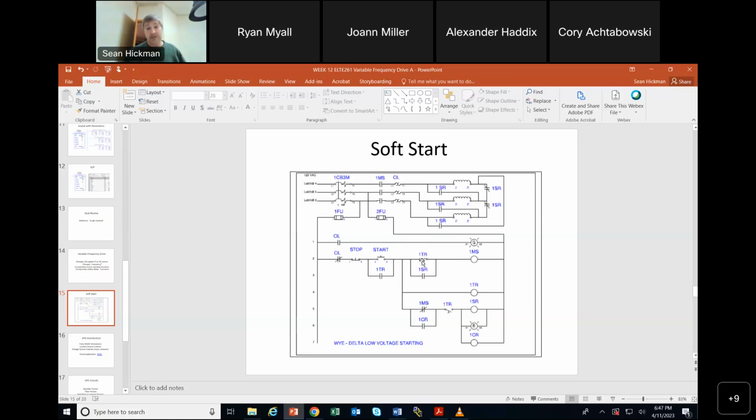And then, so we got a soft start. And then there's also some hybrid starting capabilities of the VFD, because this motor starter right here, these contacts open and close. You're turning this motor on, off, on, off, on, off. Somebody tell me what happens to these contacts right here when you turn this motor on and off like 500 times? They wear out. Yeah, they melt, they pit. You've got to change them out. You've got to service them like that, right?